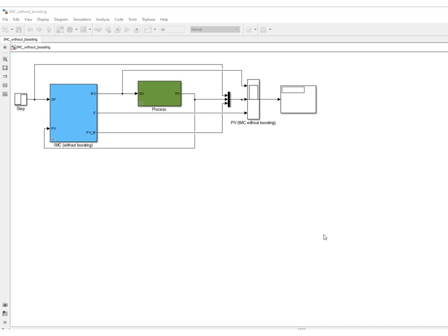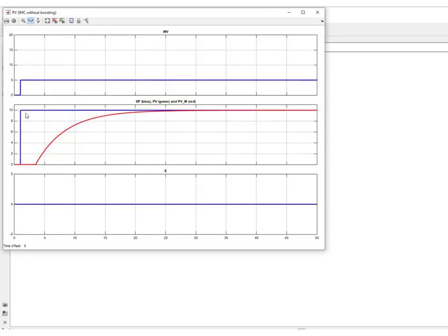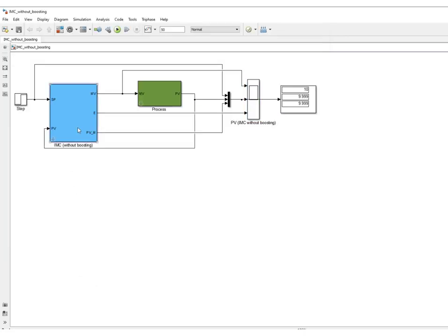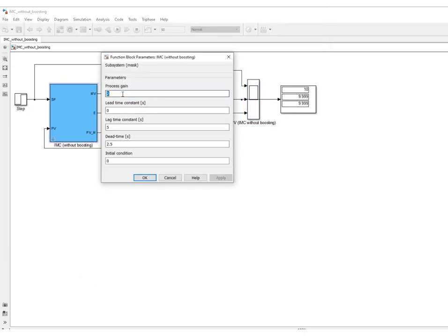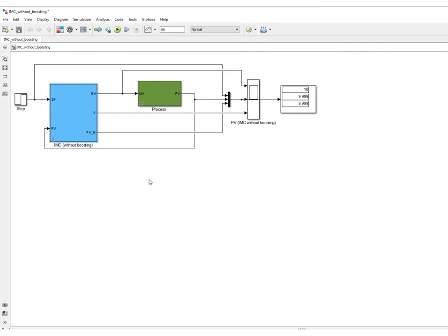To illustrate this idea that you could boost the closed loop response by decreasing the model gain, let us look at the response when the model is exact, and this is what you obtain, right? And if I now do as if the model has a gain of 1, using this static optimization, we'll divide only by 1 instead of 2, so we'll have this MV kick that will be twice as high.